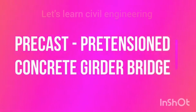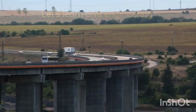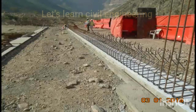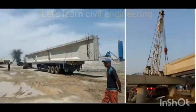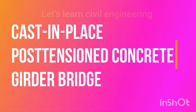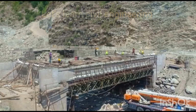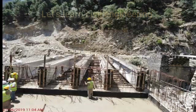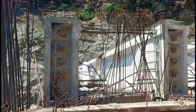Precast, pretensioned concrete girder bridge. Precast, pretensioned concrete girders are fabricated off-site using pretension techniques and then transported, erected, or launched into the project site. Cast-in-place post-tensioned pre-stressed concrete girder bridges. Cast-in-place post-tensioned concrete girders are fabricated on-site using post-tension techniques and then erected, or launched onto bridge abutments.